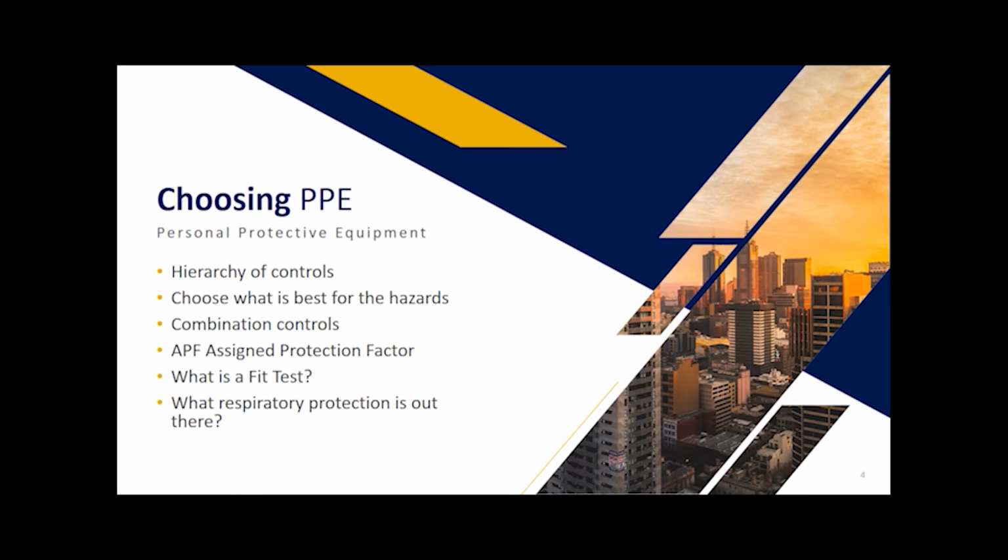So in selection of the cartridges or what kind of PPE, I do want to consider the type of particulate being generated. I would take a look at the SDS, determine what particulates are being generated, and choose a filter that would protect against that particular contaminant, particle, or hazard. It'd be the same in medical, depending on the hazards, the risks, and the contact levels.